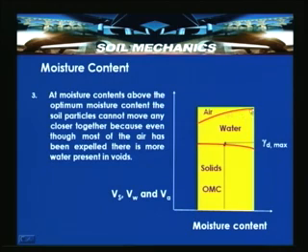We are able to shunt the air, and gradually you can see the depleting stage of the air, but it never goes to 0 here. So, you will see the depleting air. This is the volume of the air portion and this is the volume of the water portion. Once we cross this optimum moisture content, you see that the amount of water available between the voids keeps on increasing. In the process, as we have discussed, the density of water is much less than that of solids. Because of this, this also gives an explanation for why the dry density decreases with increasing moisture content on the wet side of optimum.